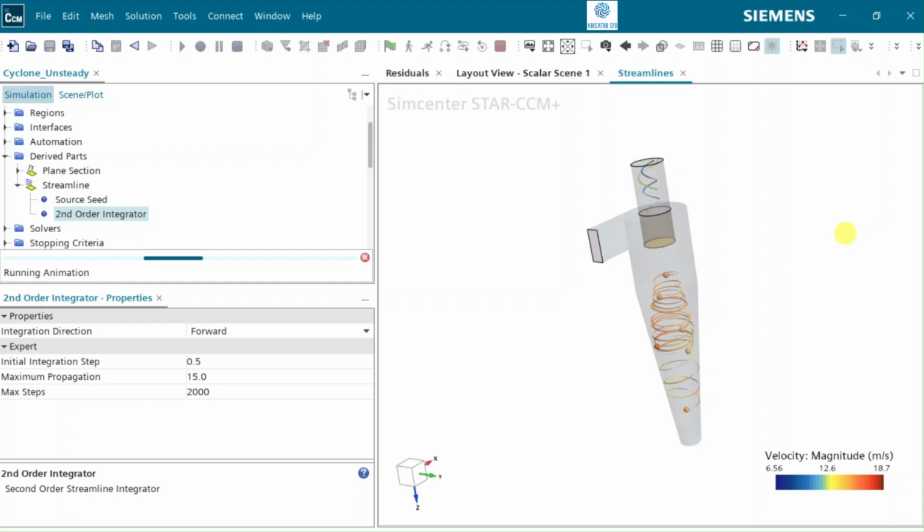So this chapter gives us a really solid CFD workflow for Cyclone Flow and STAR-CCM+, and more importantly, it shows why the modeling details matter. The combination of mesh refinement, the K-omega SST model, and curvature correction has a very visible effect on the predicted swirling core inside the separator.